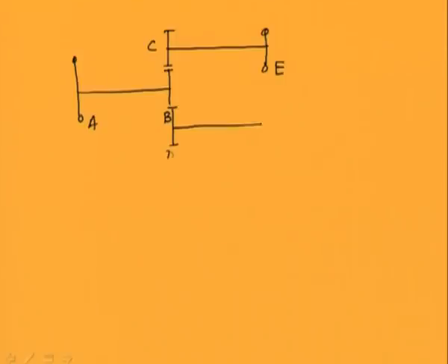Now we will take one example of a branch system in which one shaft is giving power to two shafts, and using the finite element method, for which we have already developed the elemental equations for stiffness and mass matrix, we will demonstrate the procedure. In this problem we have one rotor connected through a shaft to a gear. Let us say this rotor is A, this gear is B, this gear is connected to gear C, which itself is connected to another rotor disc E, and there is another gear D, connected to another rotor disc F.